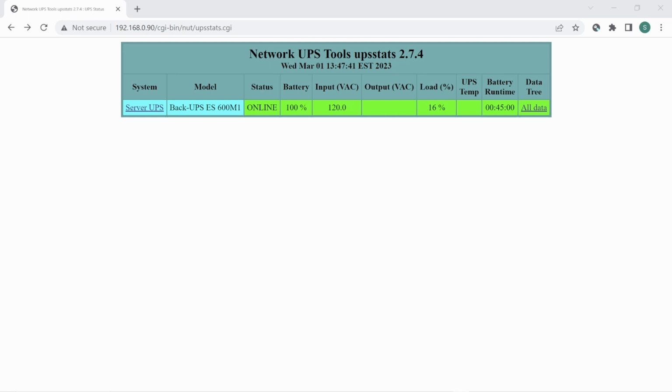The next step would be how you add the other UPSs, which are slaves. Remember the first video which I showed you, how my home is networked with 4 UPS. Right now we are looking at the UPS connected directly to La Potato. So how do you configure the parameters to make sure this server can read the other UPS details?